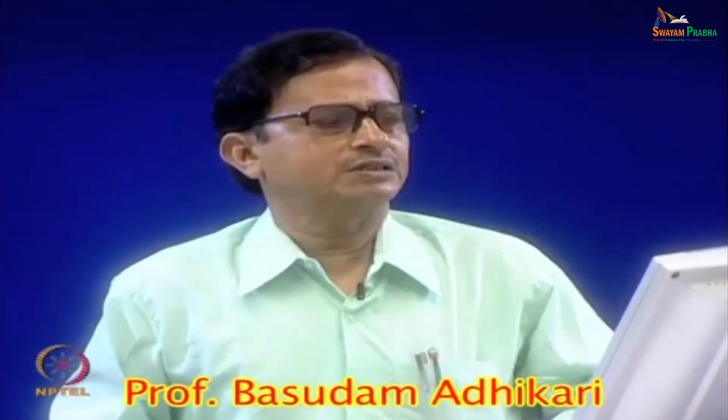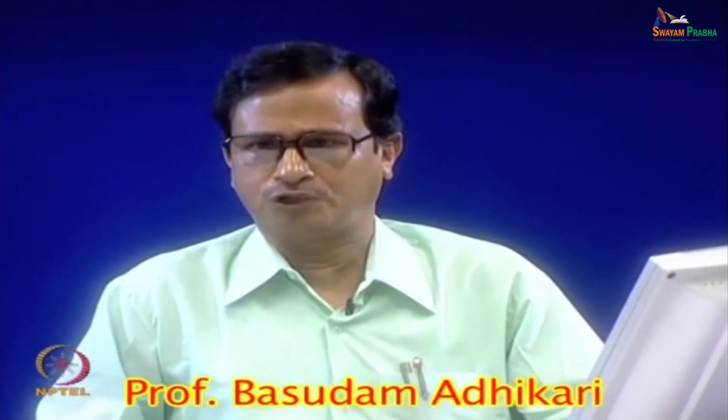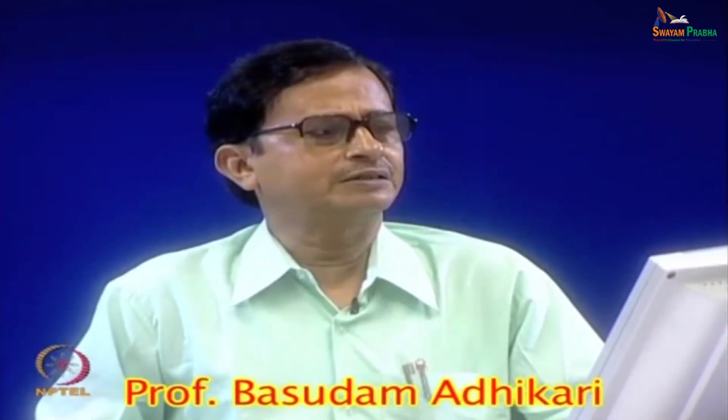Good morning. Last class we discussed the molecular weight and its distribution of polymers, and I showed that the order of weight average molecular weight greater than viscosity average molecular weight greater than number average molecular weight shows a polydispersity in a polymer sample.